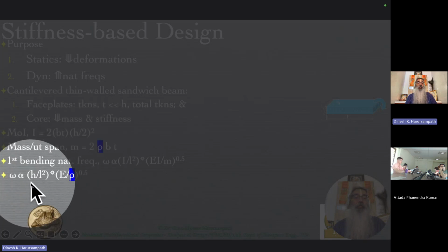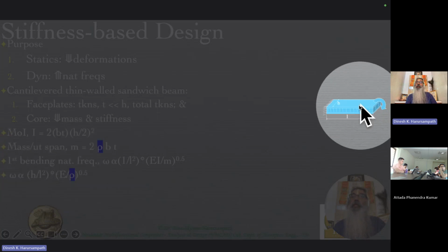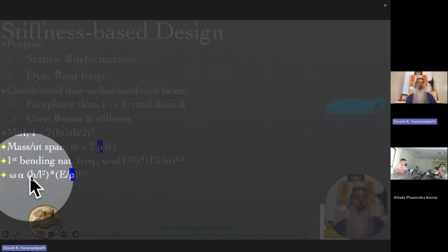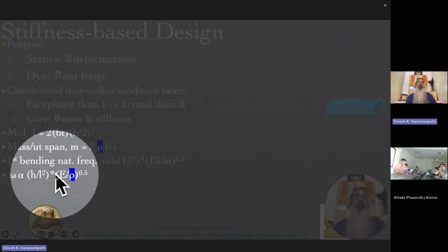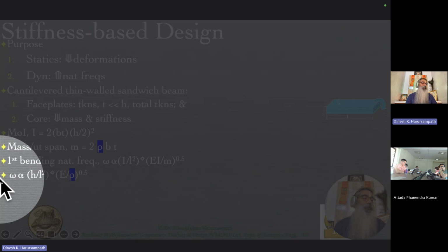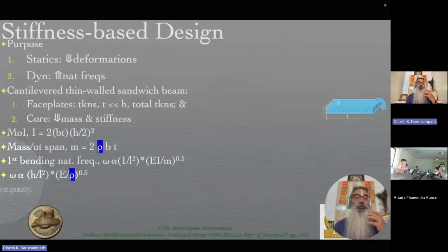And therefore, it might be possible in some cases to make the core thickness slightly larger in order to push this up if already you have chosen the material with the largest square root of E by rho amongst the choices of materials that you have for a particular component, because there are many other criteria based on which the component has to be chosen.